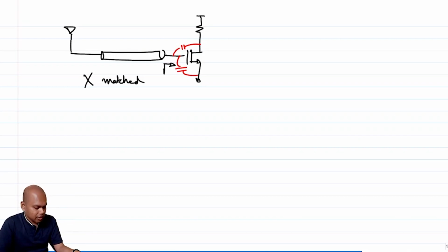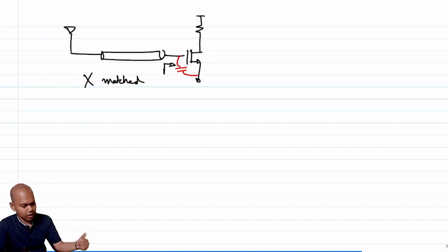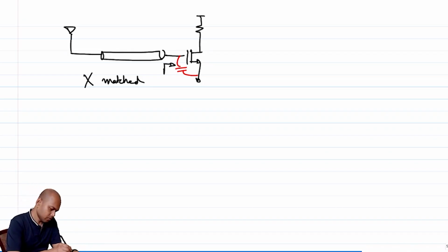And because of that, you are going to have reflections. There is no real part, although there can be a real part if I include CGD, but we'll talk about that not in today's class. You get the idea that if you have a common source amplifier, you are seeing only a capacitive impedance, and this is not going to help in matching. So what else can I do?